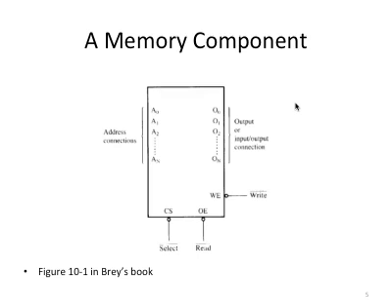There is a set of pins called address pins, usually numbered from A0 through AN, so we have N plus 1 pins used for address. On the other hand, you have output, or in some cases, input or output connections. These are data pins, represented using O0, O1 through ON.